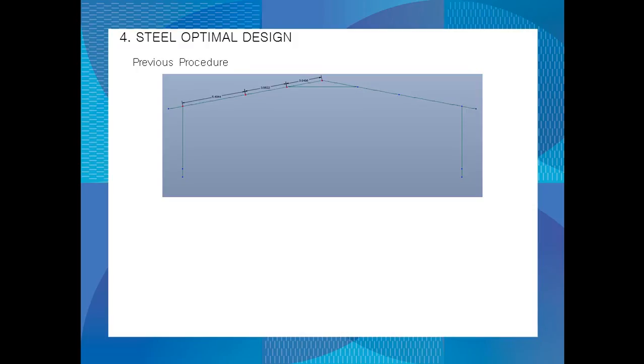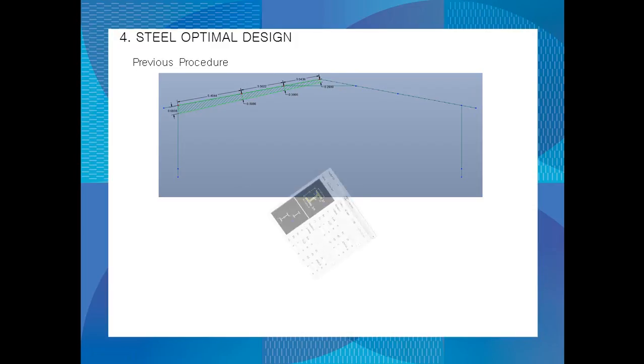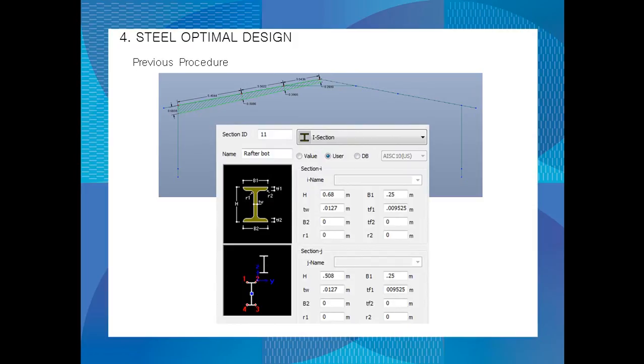What I would do is measure first the distance of a member, or between the nodes, and I would give an arbitrary section due to experience. For instance, this one here, I would make the end 0.68 and at the topmost 0.29. Take note, this is all arbitrary and it would take an iterative process. So I'm just showing this is how I would do it.